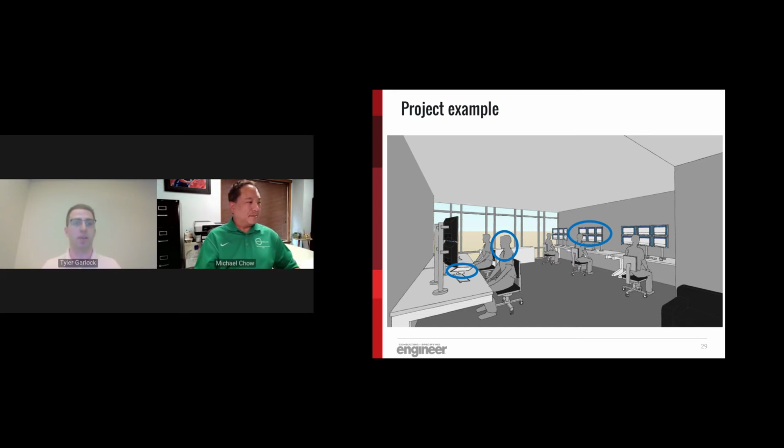So then the question became, with that wall glazing, what was the time frame this space was going to be used for? Given that it's telehealth, it could be used 24/7. So we have to consider nighttime versus daytime, and the light levels that need to be in there. Then there's also the fact that they're on camera, so we have to make sure there's lights on the face, lights on the task plane where the doctors can write notes as they're on these health visits, and that sort of thing.